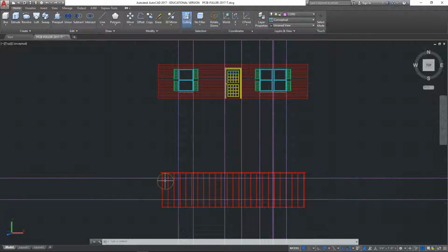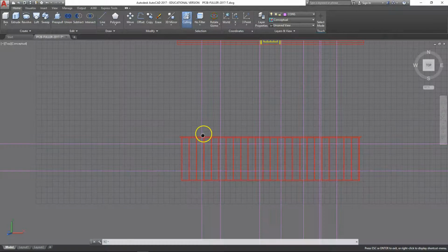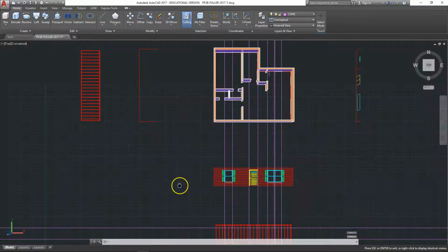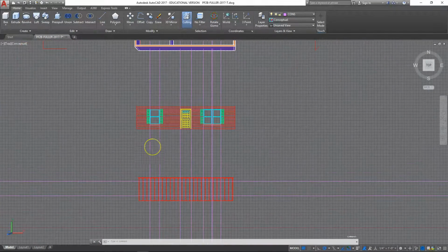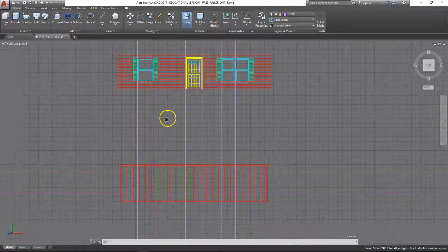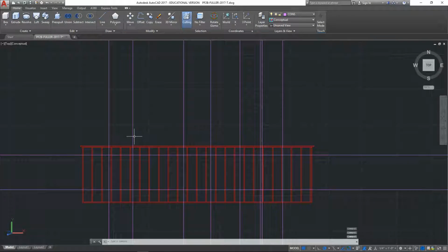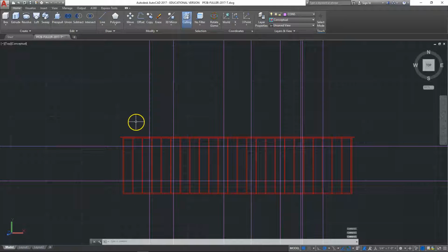If you remember, the framing of the west wall was made 5 7/8 inches shorter on each end than the wall itself to account for thickness of the material exterior to the framing core. On the front wall, this same consideration must be taken. However, an additional 3.5 inches must be removed at each end because the wall coming perpendicular from behind will cozy up in the pocket under an extended top plate.